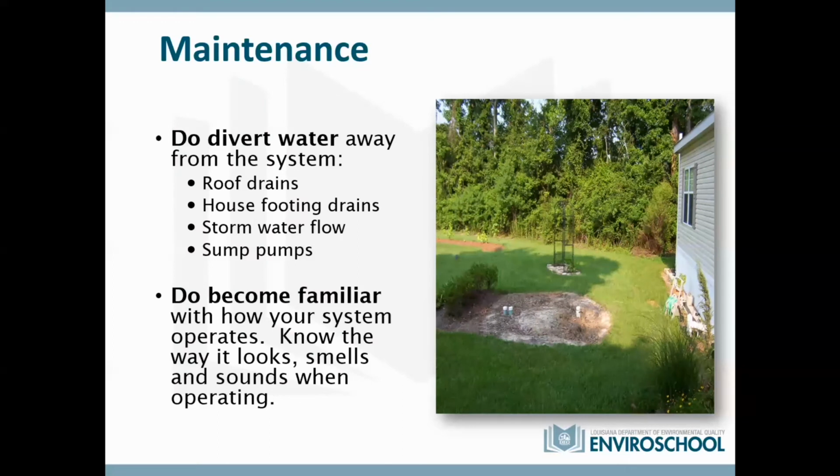Try to make sure it never gets inundated. I know in Louisiana it's pretty hard because we get a lot of inundation all the time, but water getting into these field lines or standing water over your tank can infiltrate that system. Some of these tanks, if you get enough water, can actually pop out of the ground. I've seen that with some of the hurricanes that we've had.